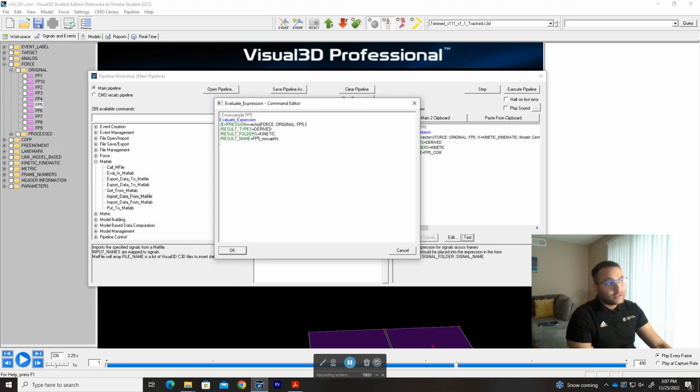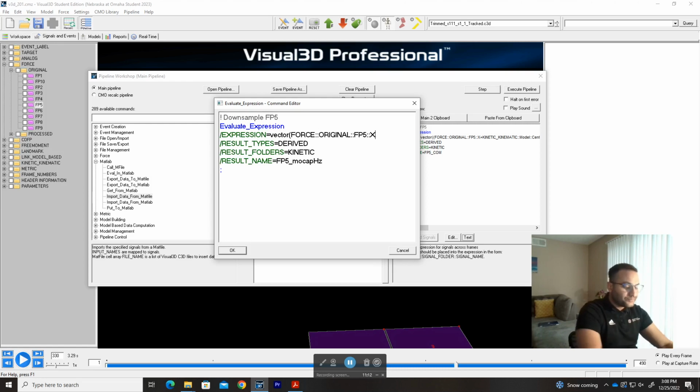You have to specify the actual coordinates, so x or y or z. So let's try x. In MATLAB, if you want to choose all the rows and one column, you basically need to open up brackets and then type a colon, then a comma, and then 1 if you want to choose all the rows for the first column.